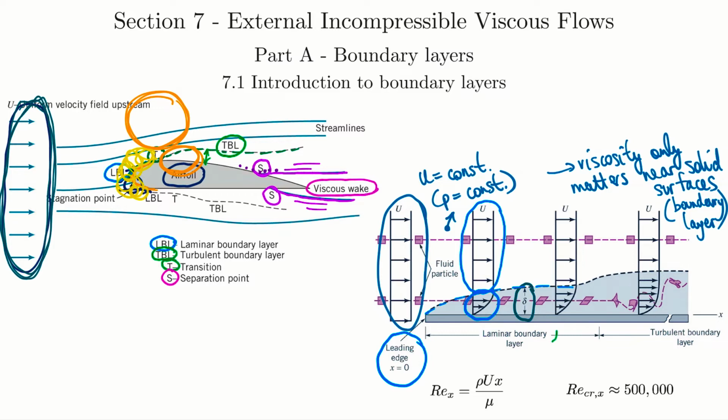Then we've got the laminar boundary layer shown here. A certain portion from the leading edge will develop as a laminar boundary layer first, and then you'll reach a point of transition, which is shown again with the increased growth. That's how we generally show it, because at the transition point, the thickness increases faster in a turbulent boundary layer. So then you have turbulent boundary layer from here on in. And as we saw in section 6, there are some real basic differences in treating laminar and turbulent flows. When the flow is laminar, we tend to be able to use analytical expressions, and the mathematics are a little more simple. And then for turbulent, we move to experimental measurements.